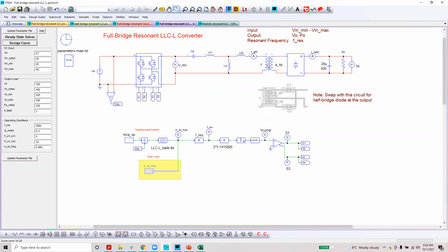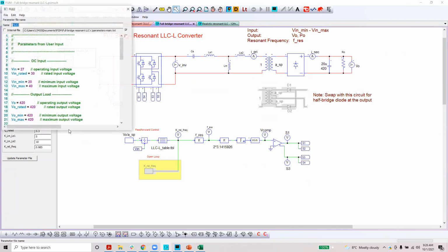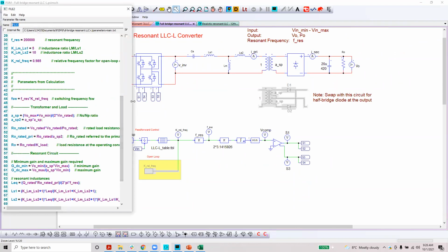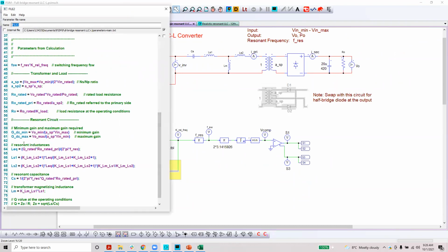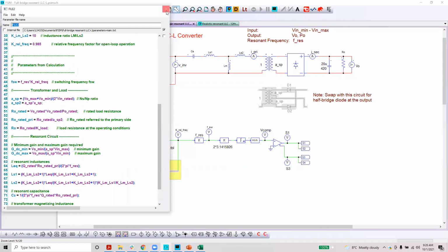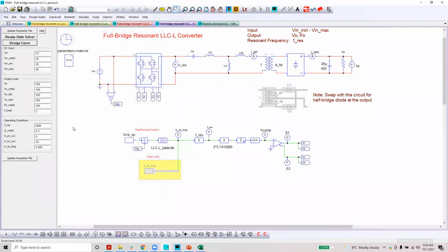And you can see all this calculation for different inductance ratios. Some standard calculation, when you select the two inductance ratio, you do it here to get your perfect value of your inductor and capacitor, and taking into account your quality factor too, and your resonant frequency, right? So this is also a good topology, alternative to LLC.